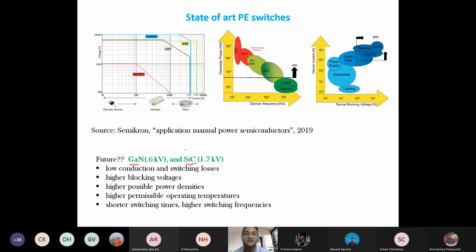So semiconductor device, you already know silicon and germanium was very popular, right? In your diode you have studied. But in power electronic systems, we mostly use silicon devices, not germanium. Okay, silicon device is presently the main constituting material for the switches. But the next coming thing, which has already come up and is still improving, but is not matured yet, is this gallium nitride and silicon carbide.